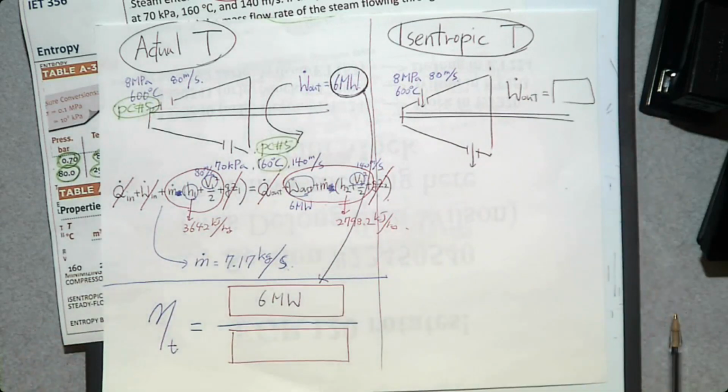Now there's a problem. Here is important. So this turbine is going to produce more power than this one. That we know. Then, if this one produces more power, how much thermal energy at the exit should there be, less than here? Because this one produces more, there is less energy left in the steam.